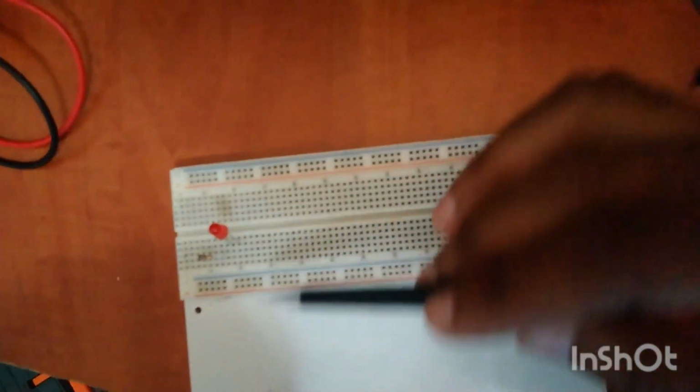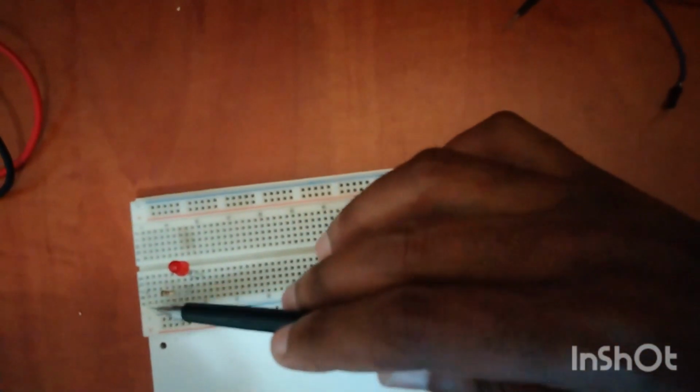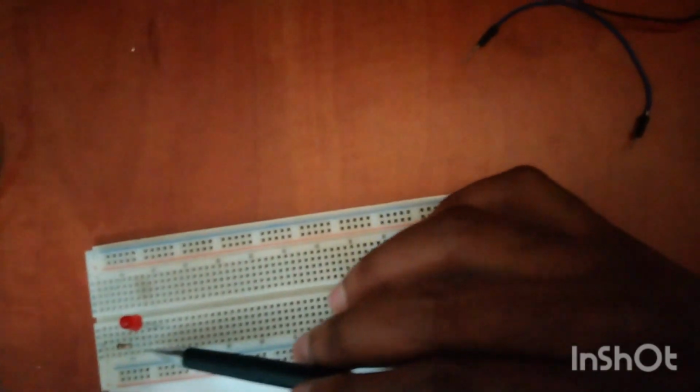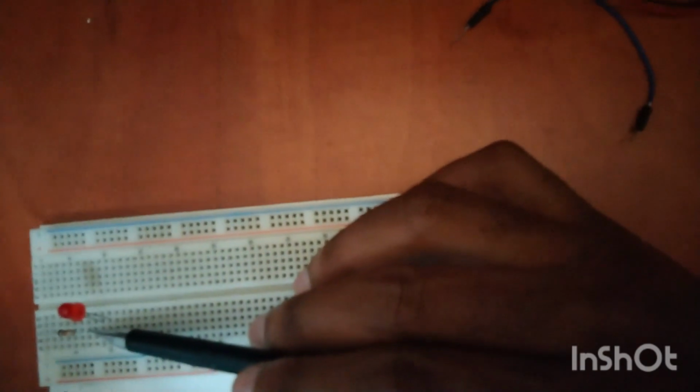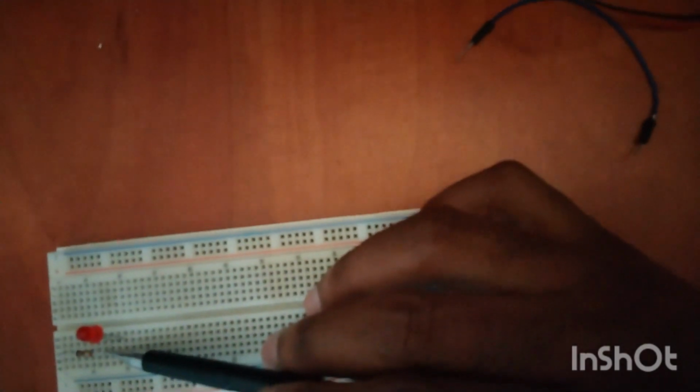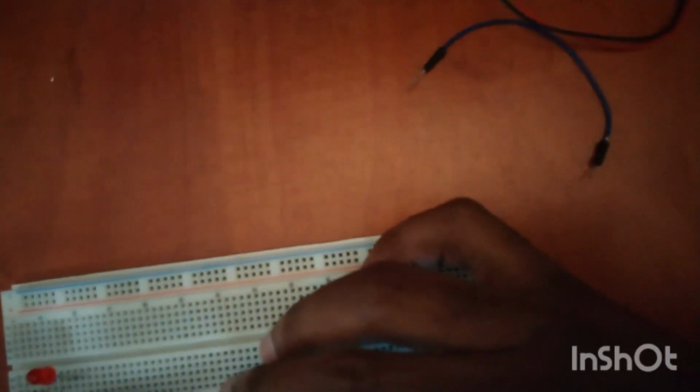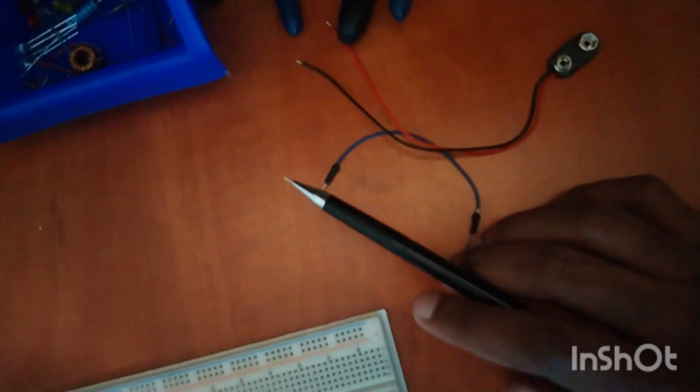Are you done? Sure. Okay. Now where is the wire now from the positive rail to A? And then if you check your resistor, you see it ends here. But now your diode, your LED, is supposed to start here, in line with this. Yours are not in line. You see, your resistor is here and your LED is here, so it's not going to light. Correct it. I'll come back again.